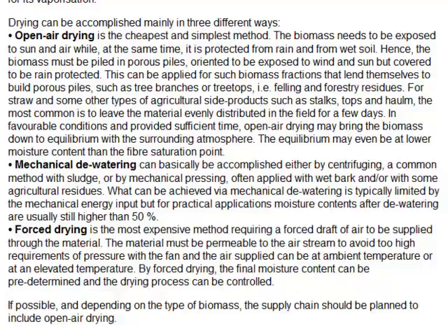So storing biomass outdoors in covered windrows or in covered piles that are not compacted but porous, so that wind gets access to it, oriented in such a way that sun can shine onto them, and storing it like that for a number of months can bring down the water content from the 50 to 60% or even higher in fresh biomass down to approximately 30 to 40%. This is the cheapest and best method for drying.